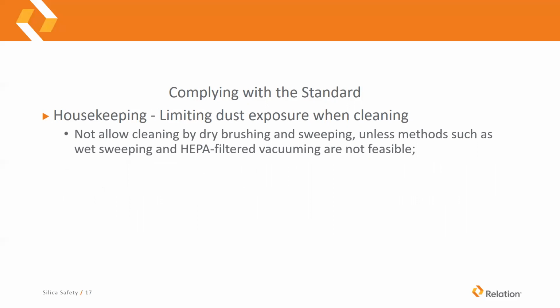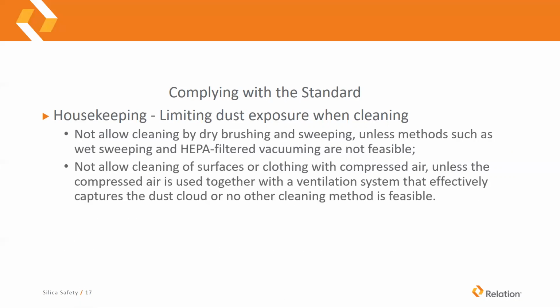We can no longer dry sweep and recreate those dust clouds. What you're supposed to be using is wet sweeping or HEPA filtered vacuums. I don't want to say shop vacs, because you can't just use a shop vac and expect all of that dust to be contained, because typically there's an exhaust, and that dust is going to escape out of that exhaust. So it's got to be a HEPA filtered vacuum.